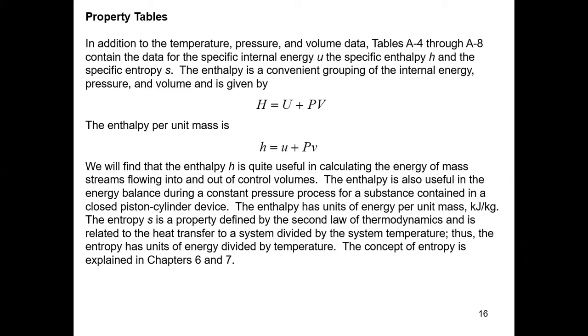We will find the enthalpy H is quite useful in calculating the energy of mass streams flowing into and out of control volumes. The enthalpy is also useful in energy balance during a constant pressure process for a substance contained in a closed piston cylinder device. The enthalpy has the units of energy per unit mass, kilojoule per kilogram. The entropy S is the property defined by the second law of thermodynamics and is related to heat transfer to a system divided by system temperature. Thus, entropy has units of energy divided by temperature.